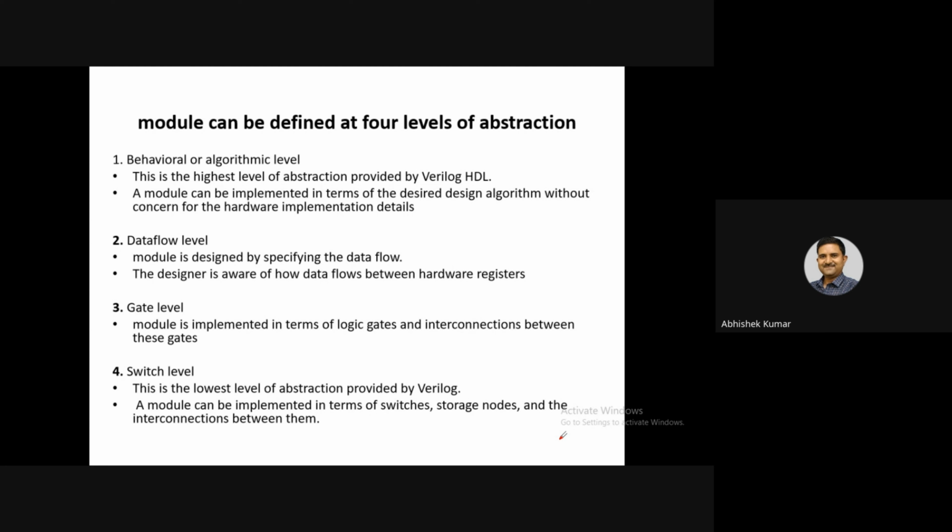So how the circuit is going to execute according to algorithms or the truth table should be defined as behavior. That's called behavioral modeling. This is known as the highest level of modeling. Here we use all the high level constructs like if else, switch case, loop statements, tasks and functions. So we can use all the high level constructs in behavioral modeling.